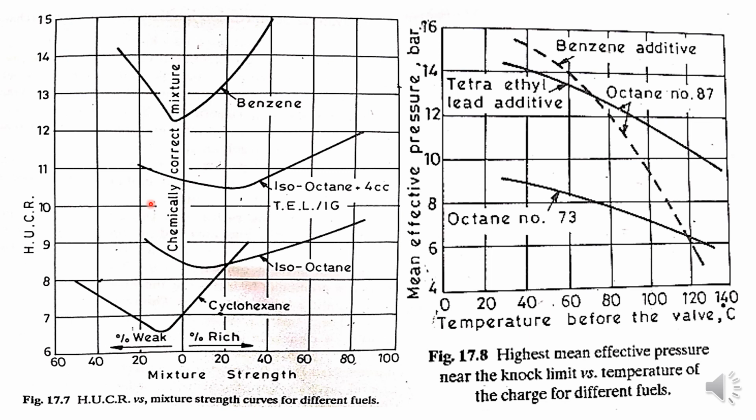So this knocking limit depends upon the type of fuel used, mixture strength, spark advance, and so many other factors. Among these, supercharging also comes into the picture. Different fuels with different knocking tendencies can be used. Some are more sensitive to increased pressure, others to increased temperature.